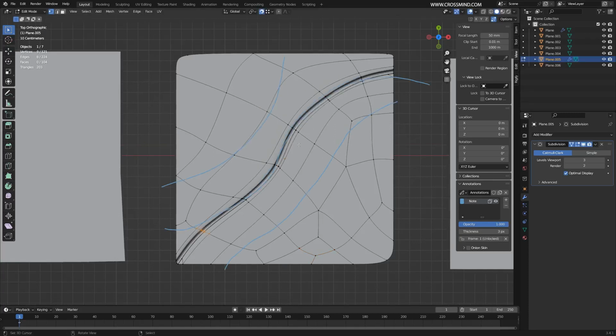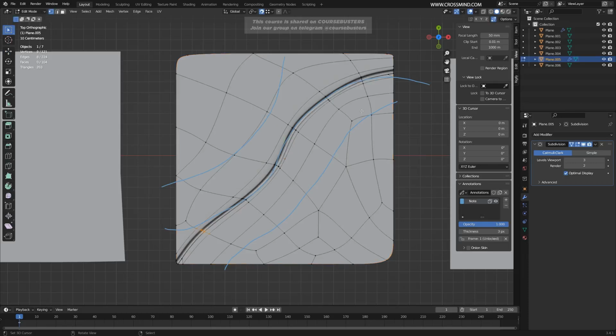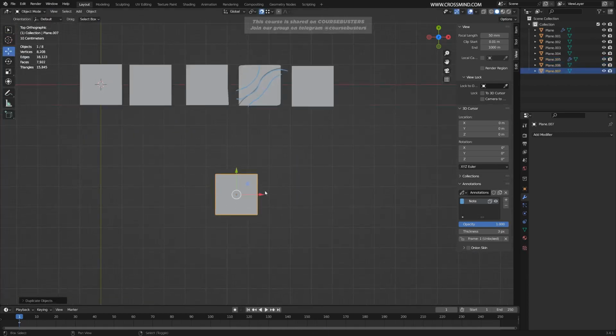So to modify it into a custom flow, just make a cut first, make sure it's all quads, then connect the triangles and n-gons, shape the surrounding edges, and then you start seeing a slightly clearer visualization of where you need to be. Then delete a few of the edges and connect and make more quads. Now let's start with a few more examples.